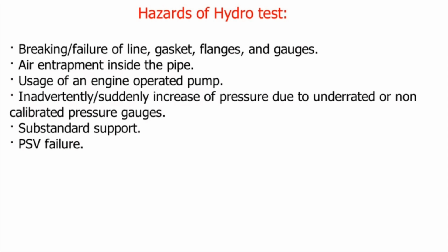Breaking, failure of line, gasket, flanges, and gauges. Air entrapment inside the pipe. Usage of an engine-operated pump. Inadvertently, suddenly increase of pressure due to underrated or non-calibrated pressure gauges. Substandard support. PSV failure.